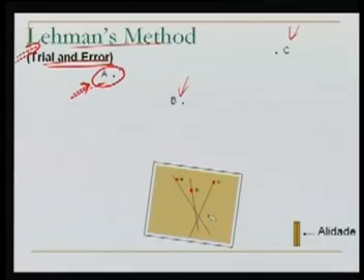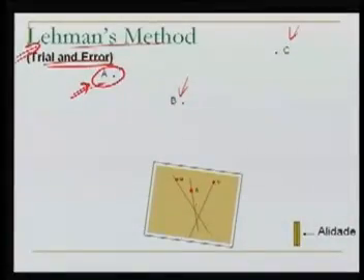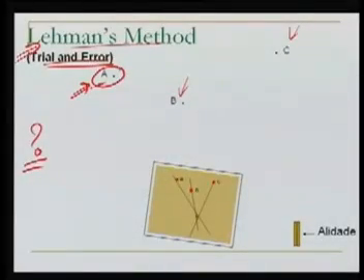So what will our effort be now? This is our first approximation. Well, our point has to be somewhere over here. It is somewhere around. That's our first approximation. For the second approximation, we'll do the iteration. So this is why this is a trial and error method. We try to reduce the error. Well, in this case, the error means this triangle of error.